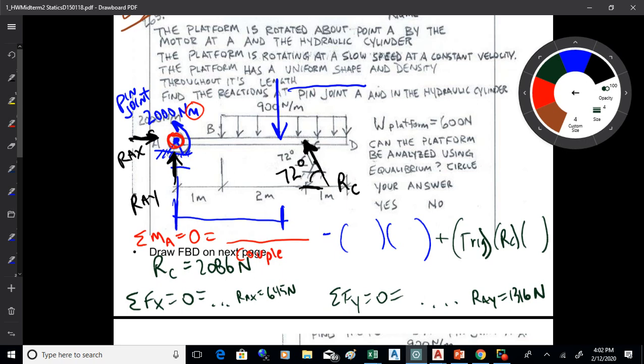All right. Yeah, question there. For the free body diagram, are we accounting for the 600 newtons of the weight of the platform too? Just at like a random, like our considered center. Yeah, okay, my bad. Yeah, that should be there. So let's get that in there too. My question would be, would it just be on the entire beam itself, not proportional to where the 900 newtons, or where you find that force coming? Right, because the platform extends that full 4-meter length. So you want to include that.